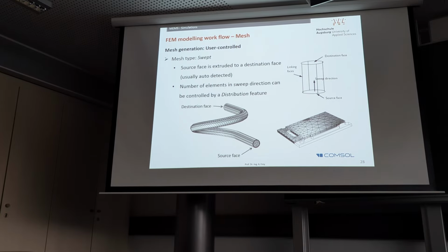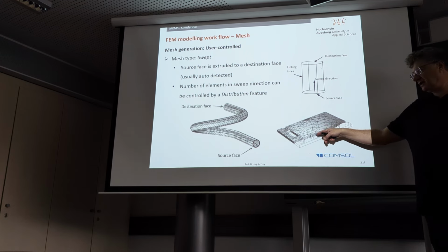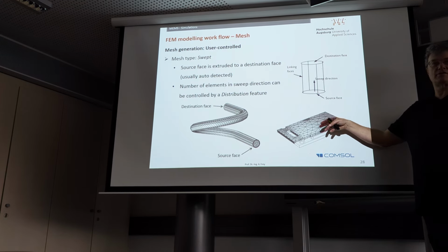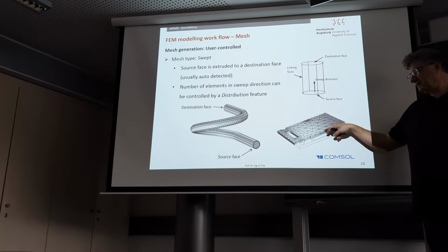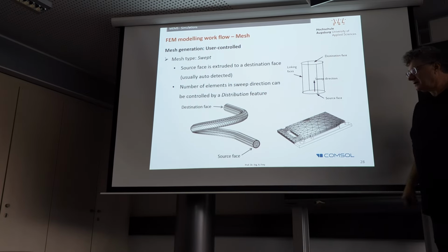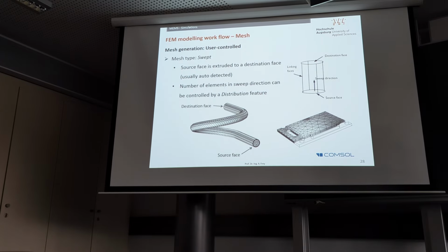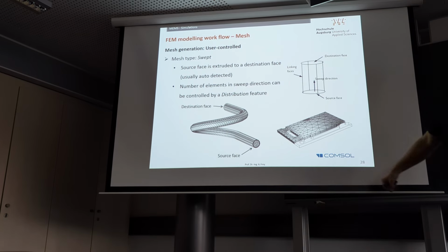And the resolution of the thin layer, because it's so thin, you can usually do kind of roughly. So that is also a situation where you usually would use such a swept user-controlled mesh to resolve the thickness of the layer.